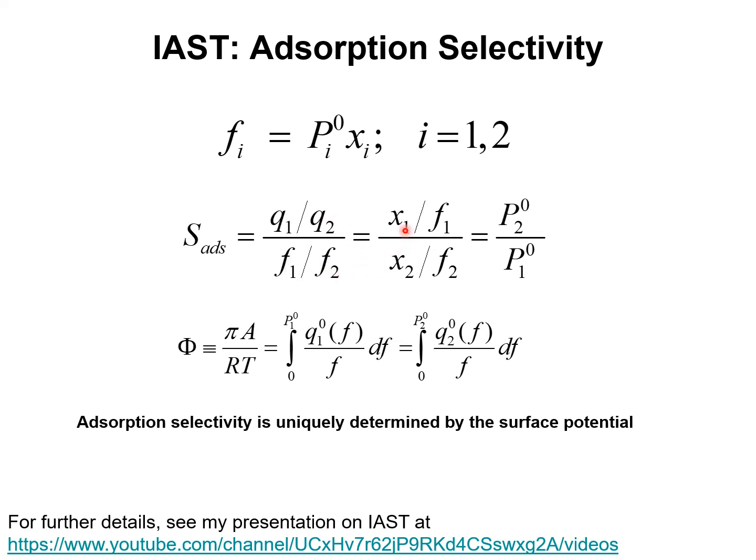This expression may be rewritten in terms of the mole fractions, x1 and x2. And in view of this expression relating the partial fugacities, sorption pressures and mole fractions, we write the adsorption selectivity of 1 with respect to 2 as the ratio of the sorption pressure of 2 with respect to the sorption pressure of 1.